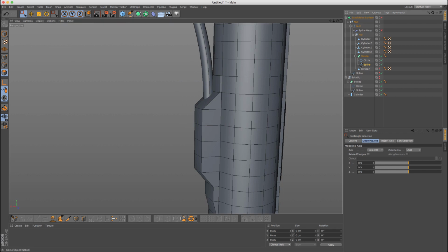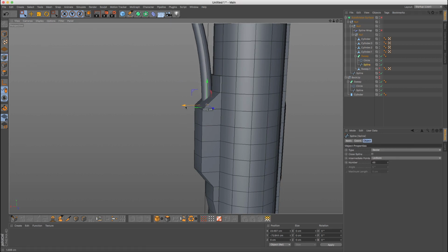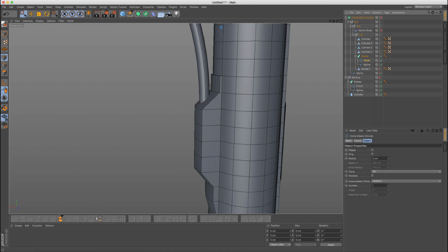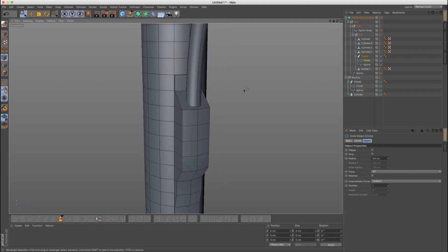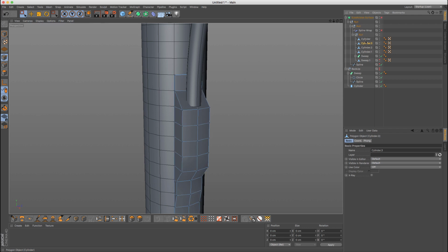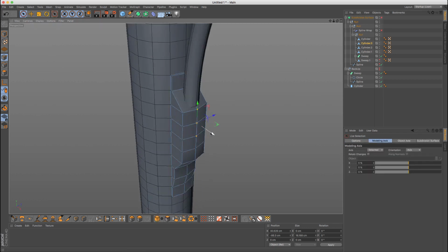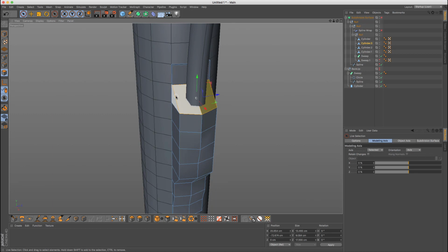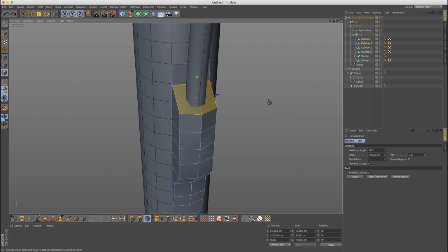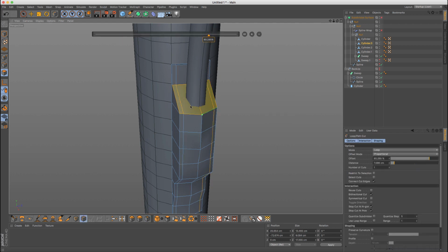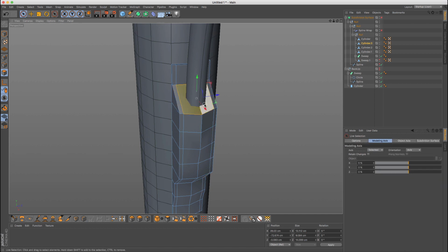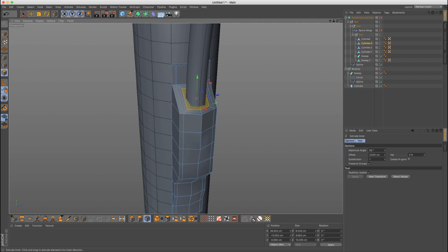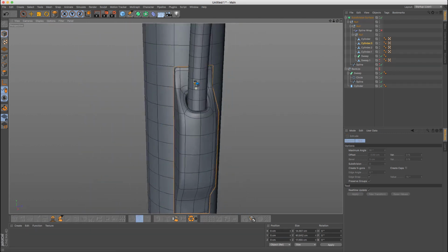We'll need to go into point mode and push it so it fits. And let's just increase the radius, something like 5, I believe, or even 4.5. Like that. Now we can come here and adjust like this. And now, before I do extrude inner like that, I would like to add a supporting edge here and here, so that I use extrude inner only at this part until this area, and then extrude it inwards. So then when we subdivide, we have something like that.